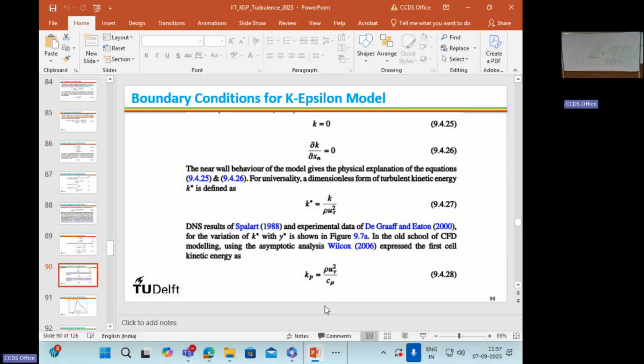That book by Durbin describes two conditions. Which one is the appropriate condition? Most CFD solvers use the second condition, that the wall normal gradient of the kinetic energy must vanish at the solid wall. Durbin has given a lengthy derivation and some justification for why to use this condition and not the other, after expanding into a second order Taylor series with mathematical calculation. But the Neumann condition, the wall normal gradient of the kinetic energy, must vanish.